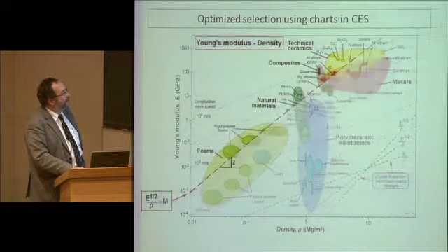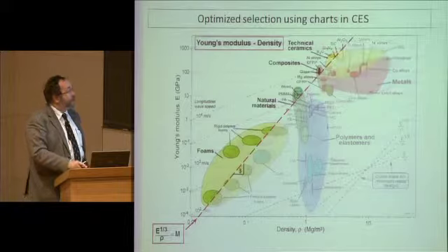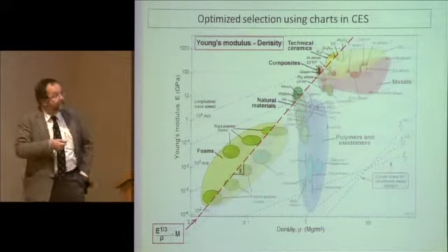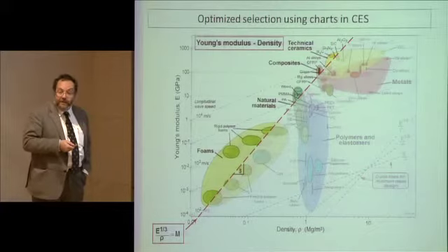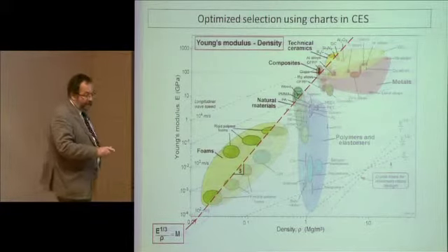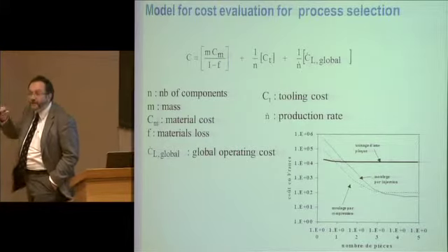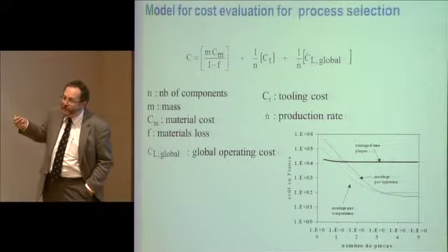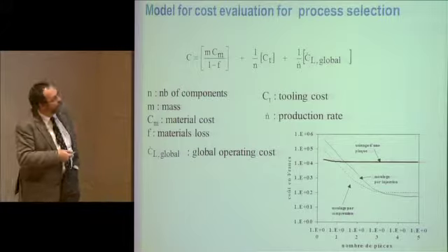So if you have modulus divided by density to the power of 1/2, or to the power of 1/3 if you were working with plates, and for each of these lines you have materials that have equal performances, that are going to have the same mass for a given strength. So that is the basic tool to allow you to compare materials for pieces of the specifications.